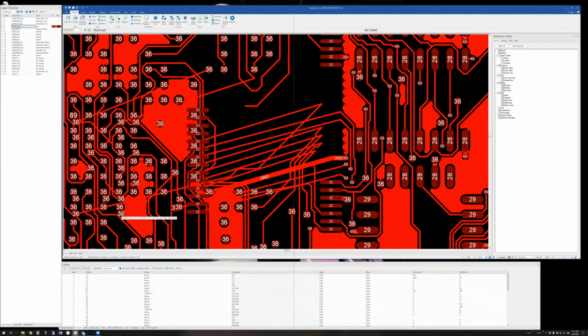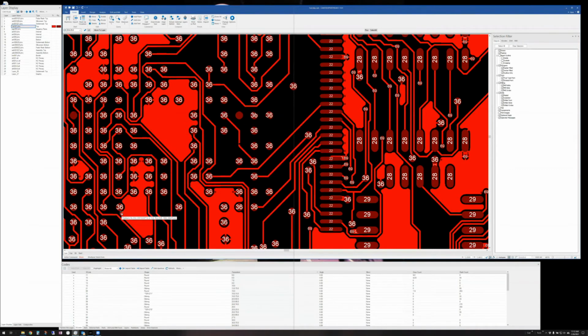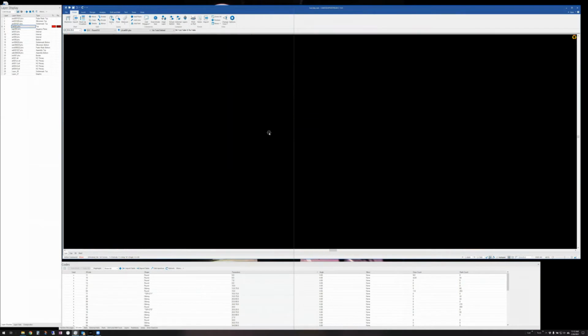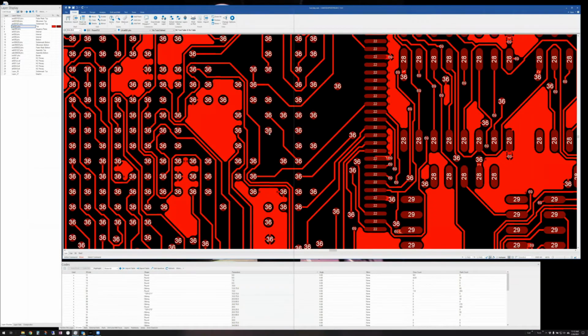As you can see, I can create a lot of havoc in the editing. Control Z works, by the way, undo. R is redraw, if you want it to redraw, if the graphics have gotten set a different way. These are all just standard commands. They've been around forever, so you're probably used to them.